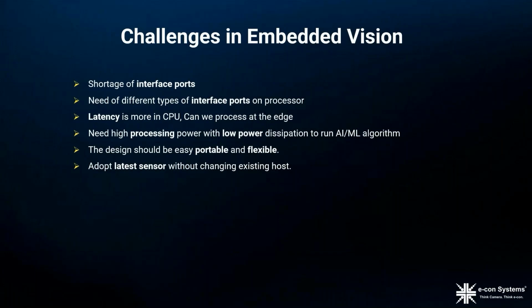The most common challenges in embedded vision products are limitations in the number of ports. That is, the processor will have 2 MIPI camera interfaces, but we may need to connect 4 MIPI cameras. The processor doesn't have the required interface ports. Or the camera is sending data in SLVS-EC interface, but the host processor has only MIPI.